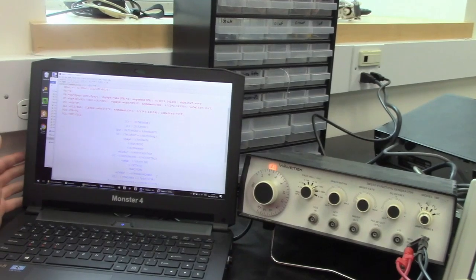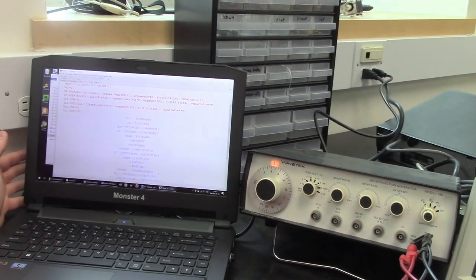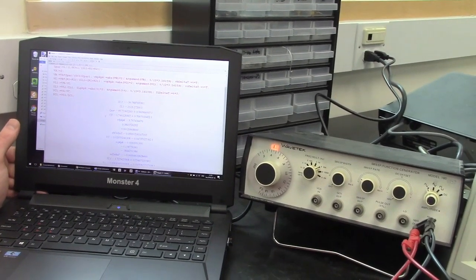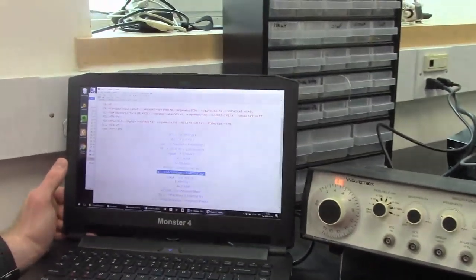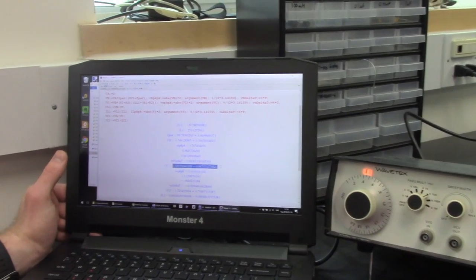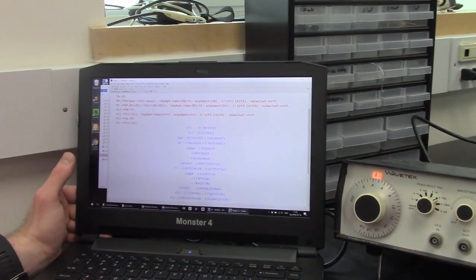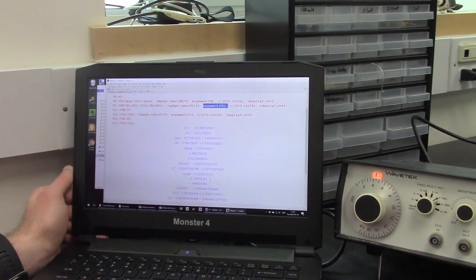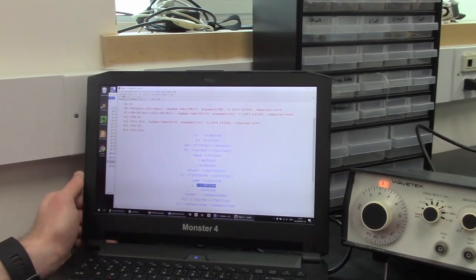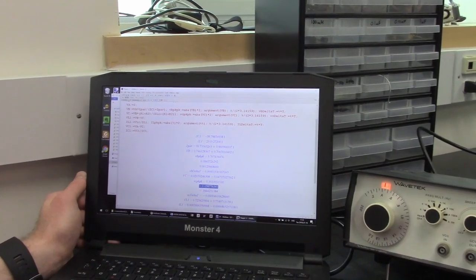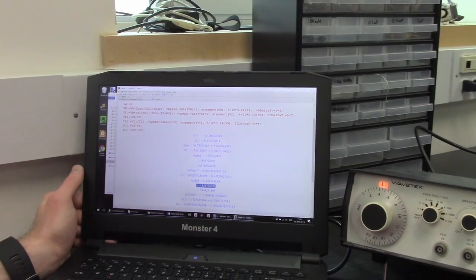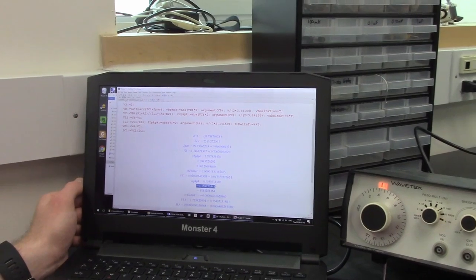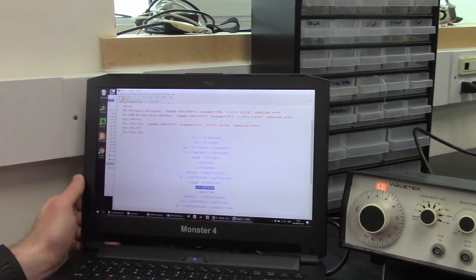So the last part is to look for the phase difference in these two measurements. When we did the analytical solution here, let's say for VC, we've got the rectangular form of the complex number here, and then by taking the argument of it, we get the phase difference. So this is in radians. To compare this to the measurement that we're getting on the scope, we need to convert it into fractions of a cycle, or even a time difference ideally.